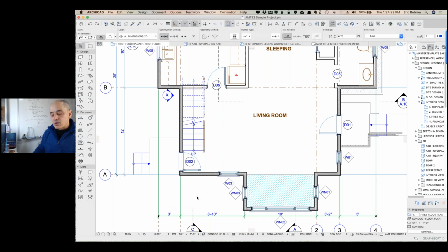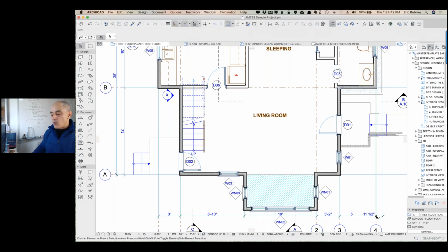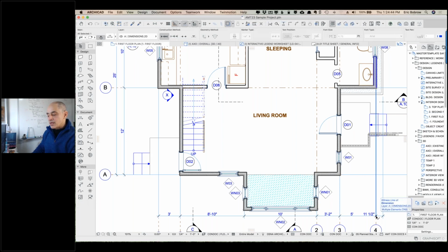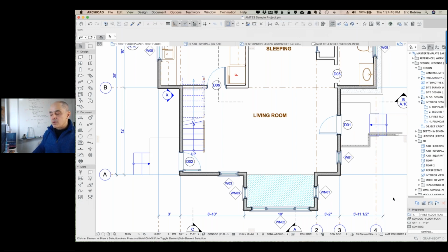But if you're talking about what I just did, where I wanted to dimension, instead of, I mean, this is a little arbitrary, but instead of going to this point, maybe I really wanted to go to that point, I can have this chain here and command click or control click on another point, and then I can get rid of the intermediate point if I don't want it by selecting that point and deleting it, and you can see how it combines.